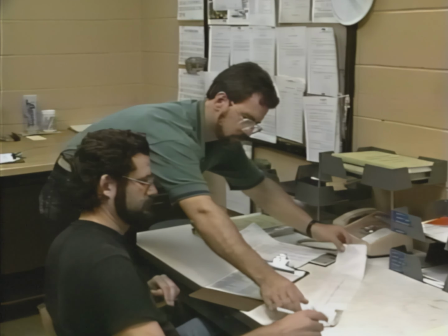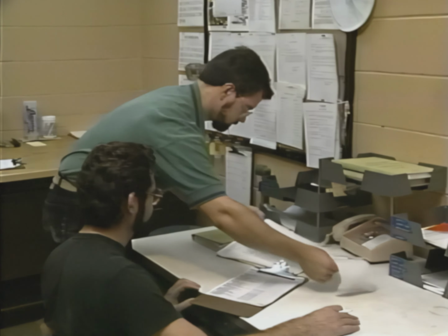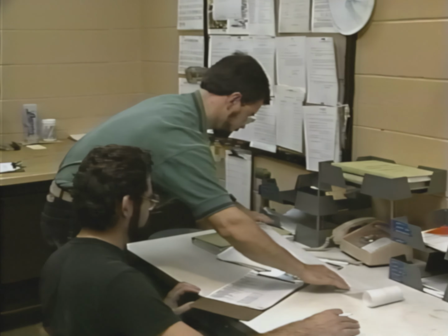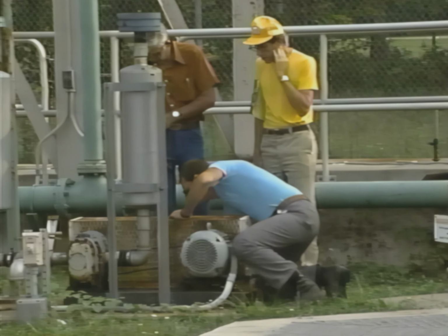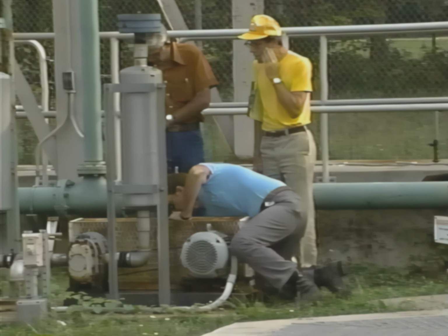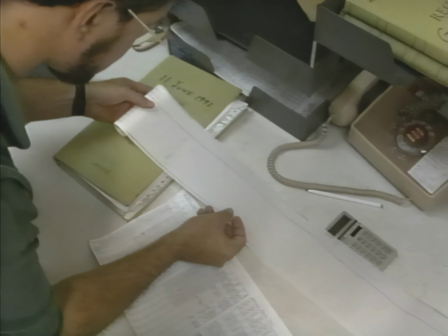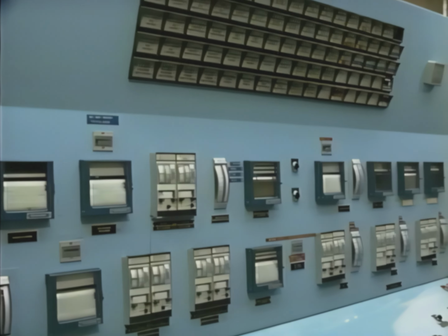Review these records and note the frequency of routine operations, maintenance inspections, flow meter calibration, and the uniformity of the flows reported. Quality control areas to evaluate include the proper operation and maintenance of equipment, accuracy of records, valid flow measurement techniques, precision of the flow data, and frequency of calibration checks.